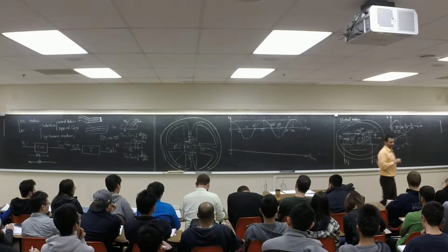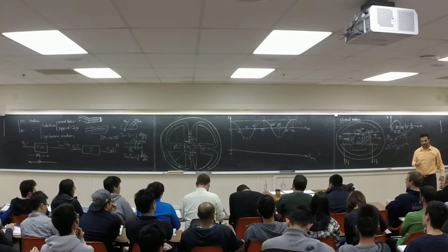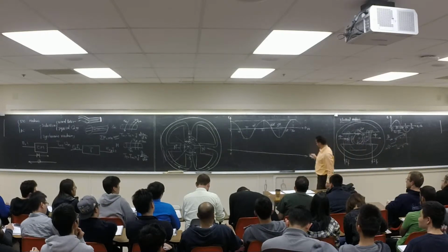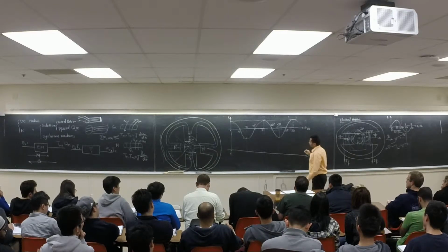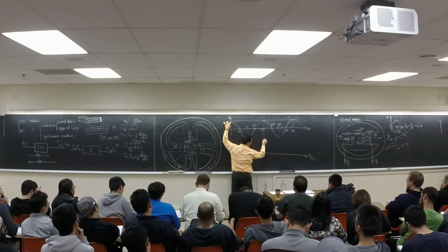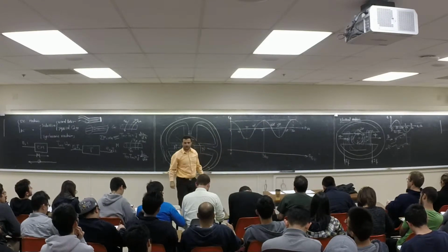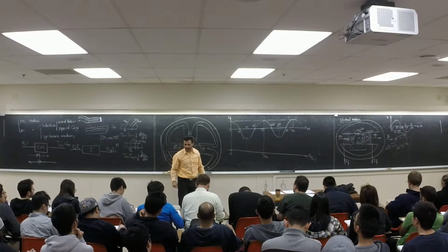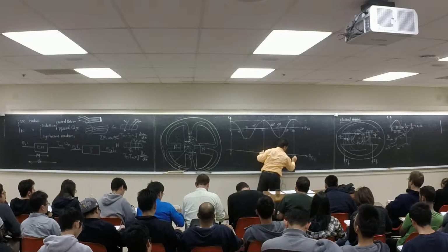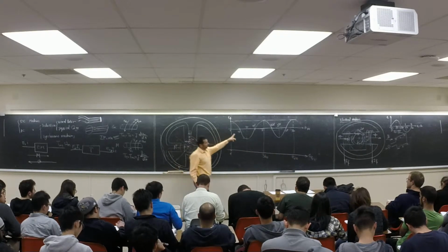How many cycles is the electrical waveform? 2, right? If you look at theta E here, from here to here is 1 cycle, right? So 1 cycle means how much? 360, right? 360 degrees. Another cycle from here to here. How much is this one? 720, right? So what I put here, I made a mistake.